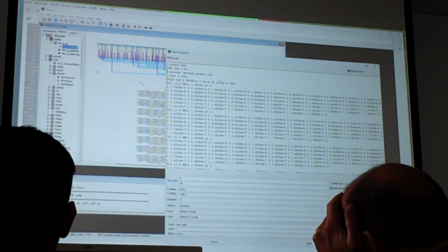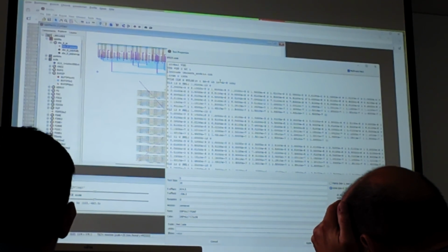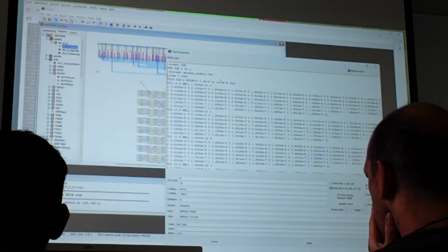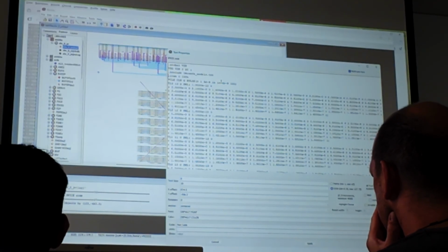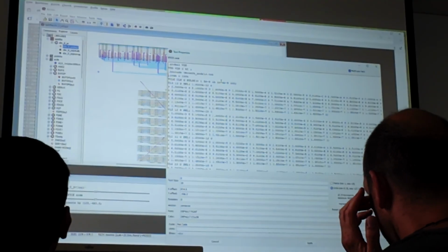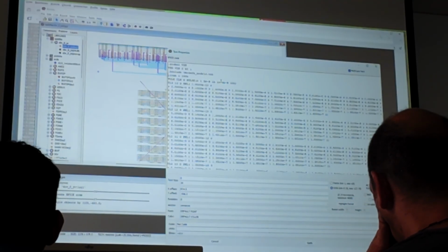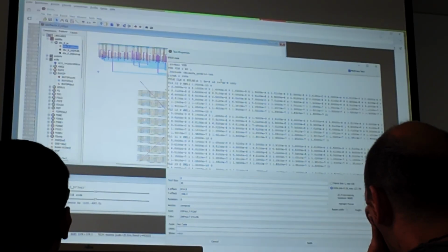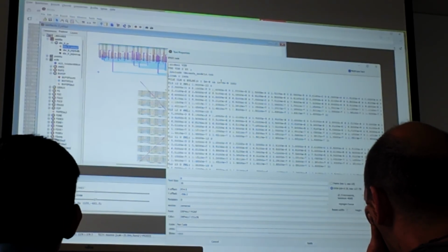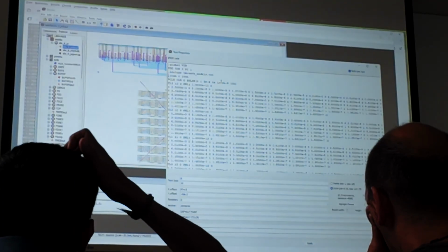Oh, okay. That I include my CMOS EDU models, so that I have a transistor model, and I want to simulate for 160 nanoseconds. Since my clock cycle is 10 nanoseconds, I have 16 stages, so I need 160 nanoseconds. And then all the things about my input signals and output signals come.